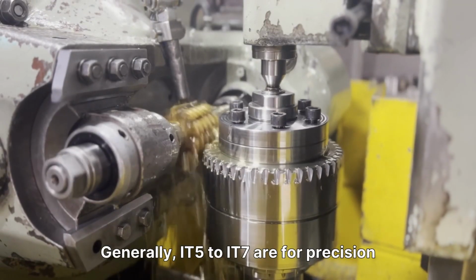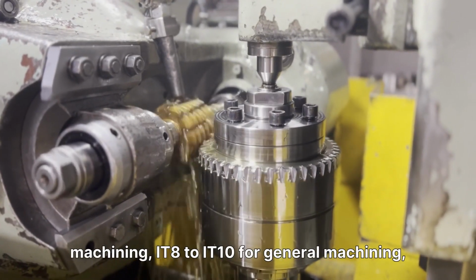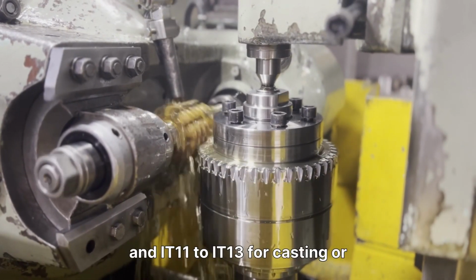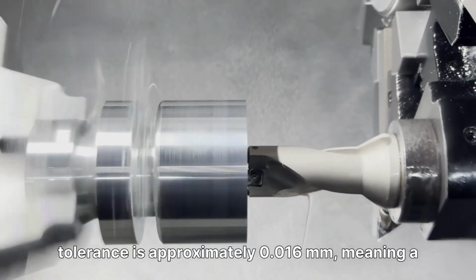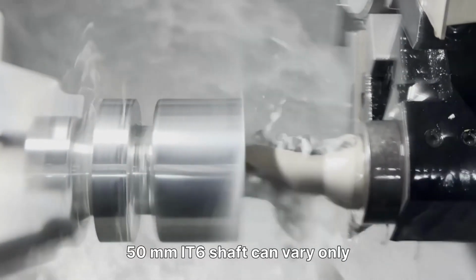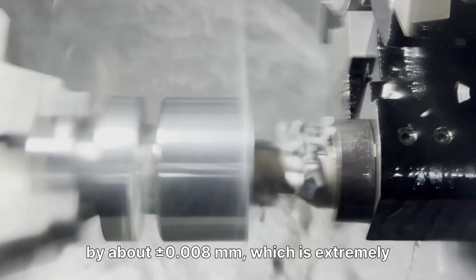Generally, IT5 to IT7 are for precision machining, IT8 to IT10 for general machining, and IT11 to IT13 for casting or forging processes. For a 50 mm size, an IT6 tolerance is approximately 0.016 millimeters, meaning a 50 mm IT6 shaft can vary only by about plus or minus 0.008 millimeters, which is extremely precise.